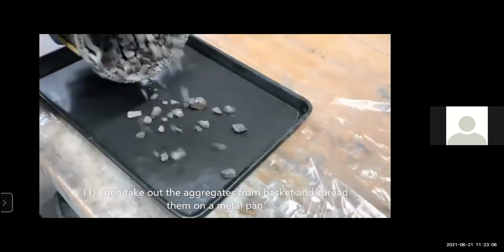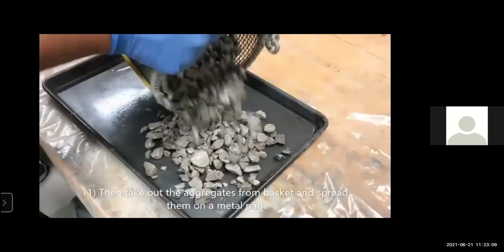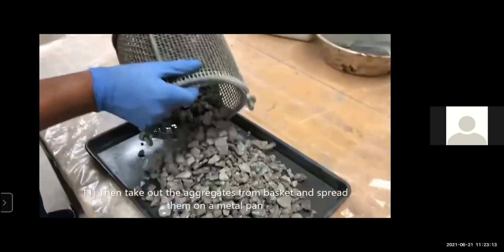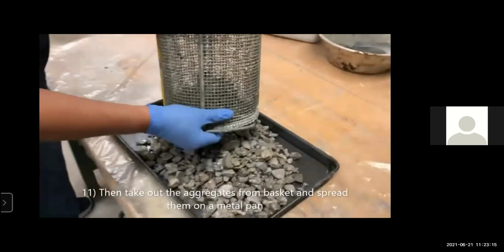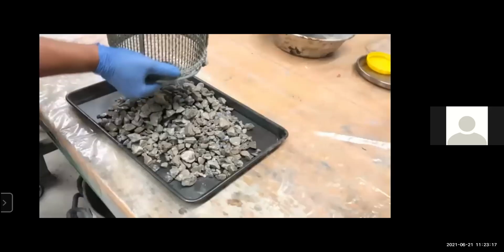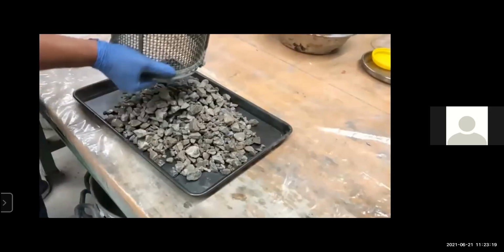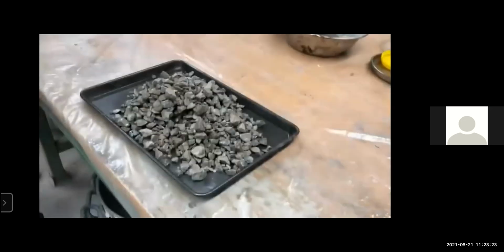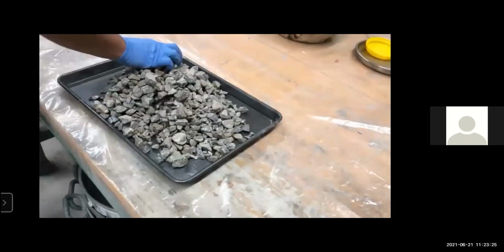Then take out the aggregate from the basket and spread it on a metal pan. After 24 hours of immersion in the water bath, take out all the aggregate from the basket and spread all the aggregates on this tray. So here we pour all our aggregate on this tray.